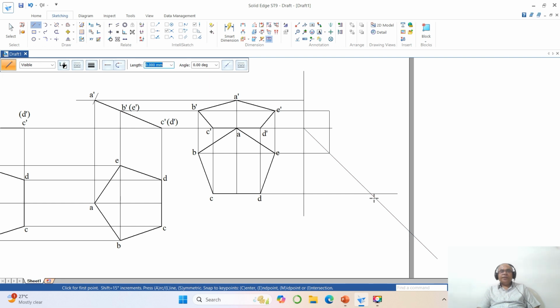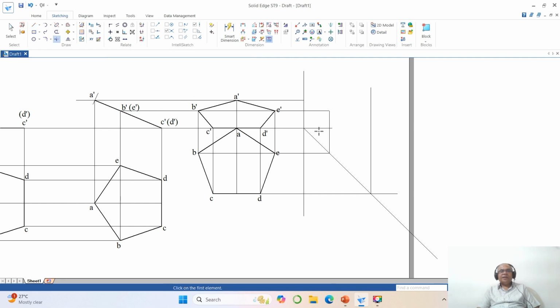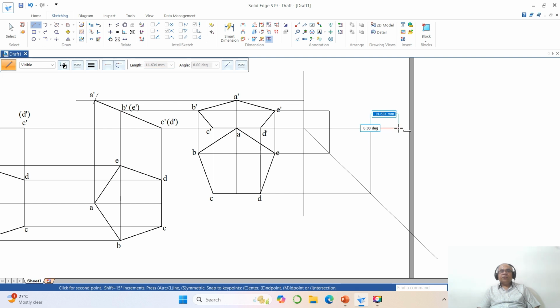Okay, from here you take this, then go to trim corner between this line and this line, so between these two. Okay, now you go to line command, draw a line from the intersection onto this side. So now you join this point to this point directly. So all these 3 points are going to lie on the same line.